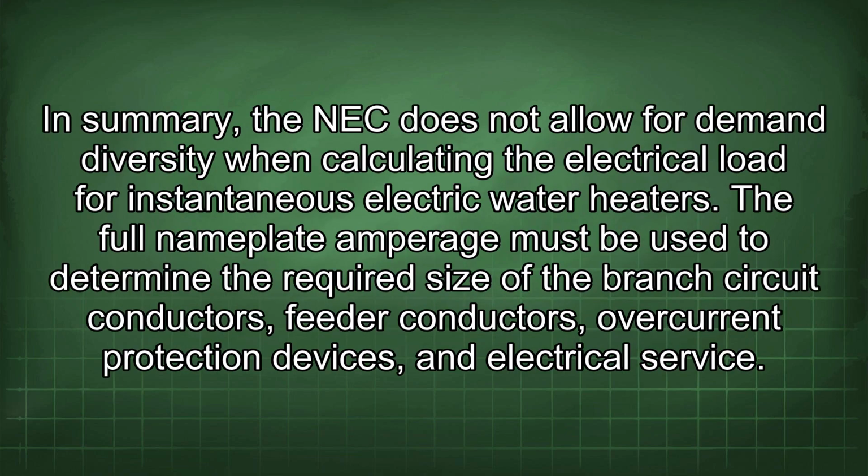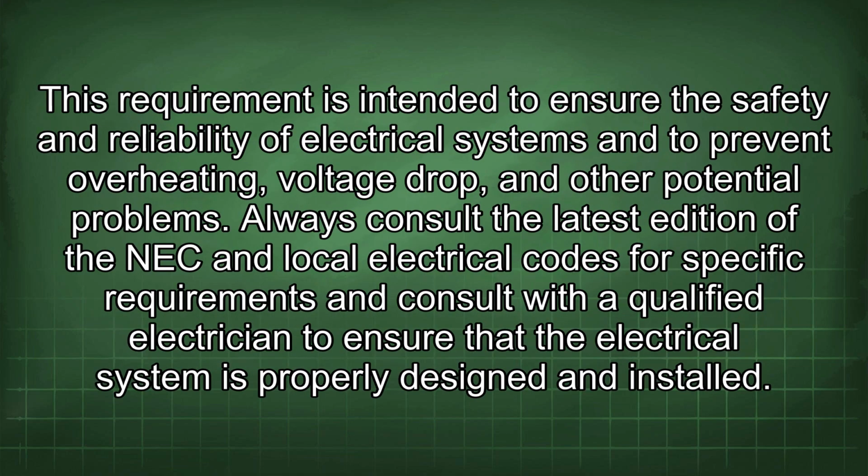In summary, the NEC does not allow for demand diversity when calculating the electrical load for instantaneous electric water heaters. The full nameplate amperage must be used to determine the required size of the branch circuit conductors, feeder conductors, overcurrent protection devices, and electrical service. This requirement is intended to ensure the safety and reliability of electrical systems and to prevent overheating, voltage drop, and other potential problems.